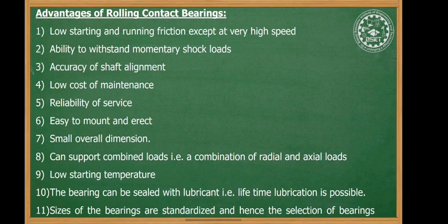Let's see the advantages of roller contact bearing. So low starting and running friction except at very high speed, ability to withstand momentary shock loads, accuracy of shaft alignment, low cost of maintenance, reliability of service, easy to mount and erect, small overall dimensions, can withstand combined loads, that is the combination of radial and axial loads, low starting temperature,